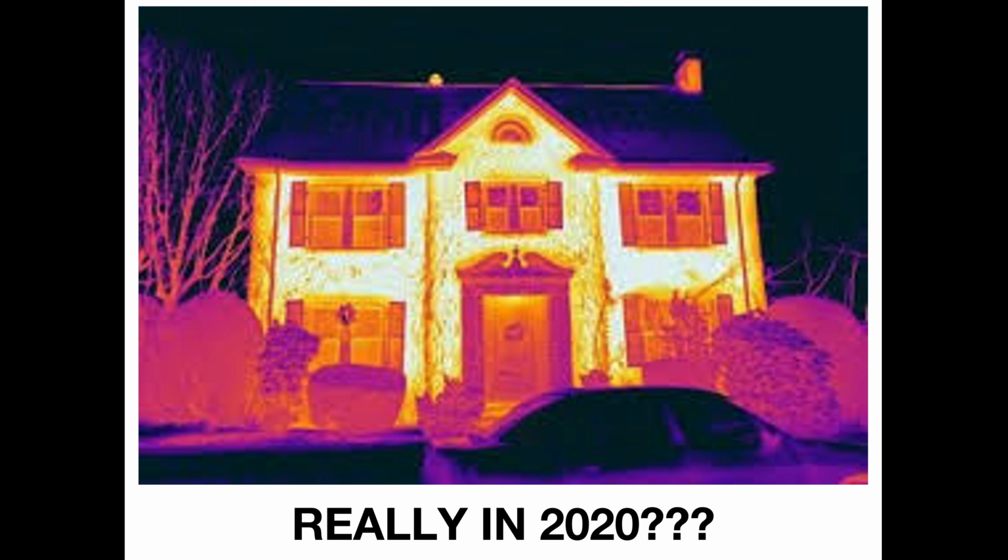Now, what we have in the UK is building regulations and what are called air change rates of up to 10 air changes per hour. Now, that is a very, very poor build if that is the case, and I don't think it would really be allowed, even though it's up to 10 air changes now. Most are down to sort of 5 and under.